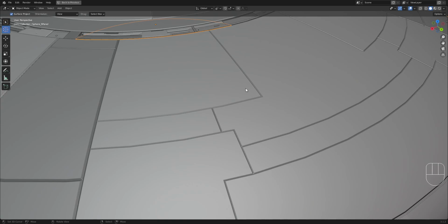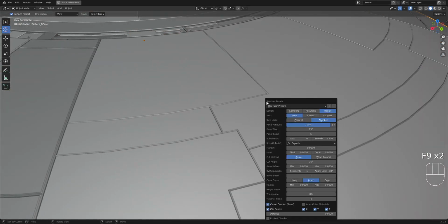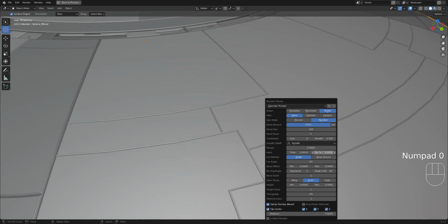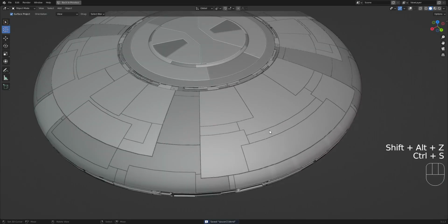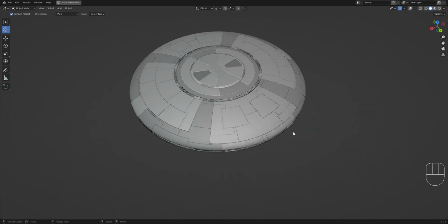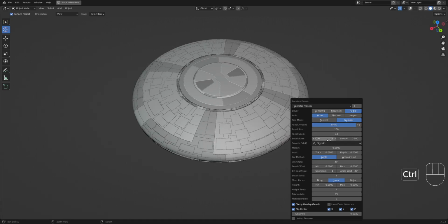So what we're going to do is make this detail look like it's a part of the mesh underneath. But we need to modify this a bit, 0.005, okay, 0.0005, and make it thinner also, maybe probably just use 0.0005 as well, okay. And we run with the result, more, okay. This area looks good, this area is not so good. Let's try and increase this, okay. No, that's too much subdivision.